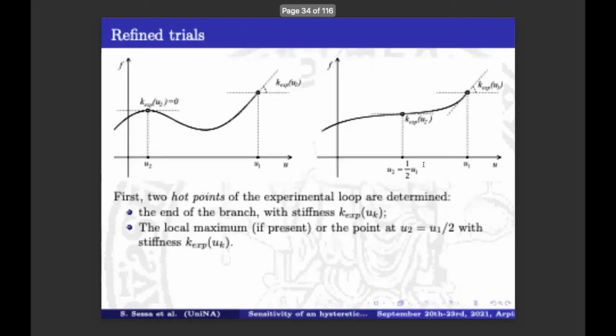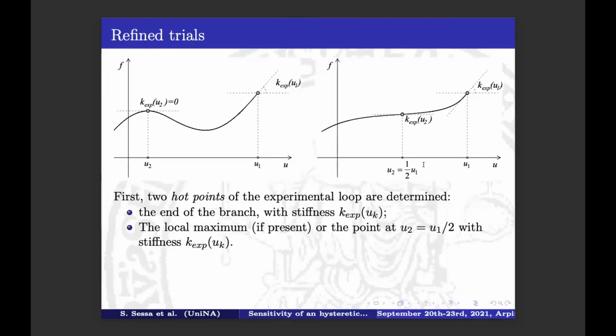This is because beta 1 and beta 2 are needed to introduce in the boundary curves some kind of behavior like these ones. For example, they are used to introduce local maxima or minima, or to adulterate the stiffness at the tip of the hysteretic loop.